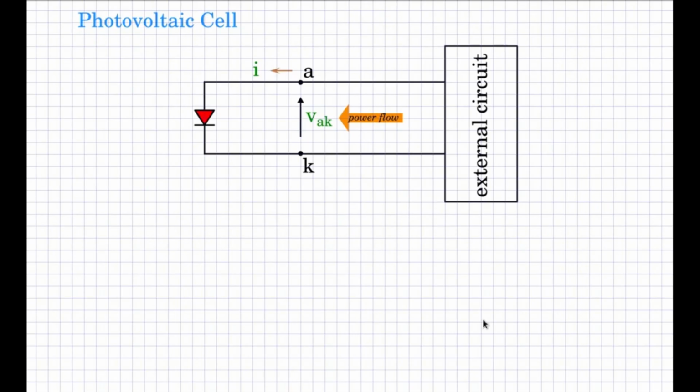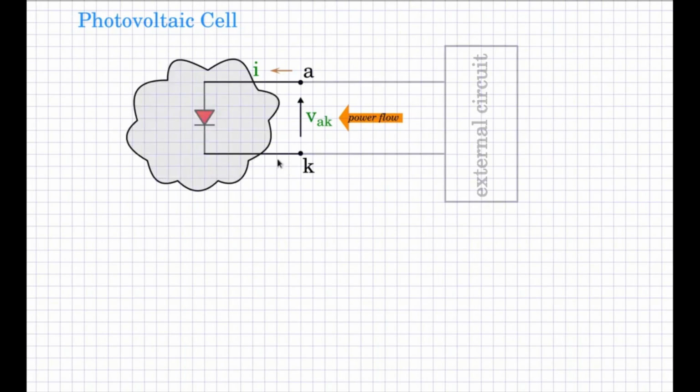The object of interest now is the diode part. So we'll bring the focus to the diode. And this diode, in its present representation as it is drawn in this circuit with the current flowing into the anode terminal, and with the voltage indicated as thus, and the power flowing into the diode terminals, the diode acts as a sink, which means it receives power and only dissipates.